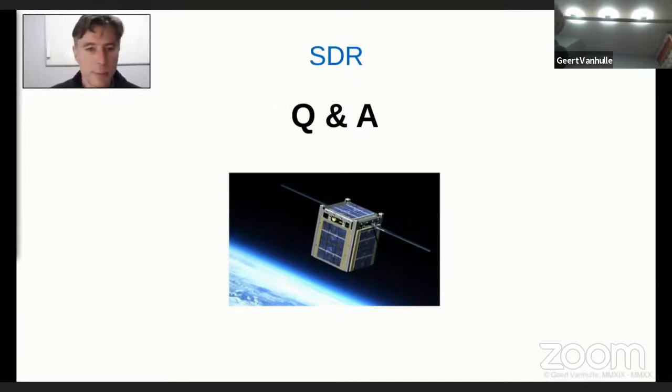The difficulty with analog propagation delays is that they are very nonlinear. So if you have a certain bandwidth, the propagation delay at a certain frequency risks being different at another frequency, which causes a huge set of problems in the analog field. In the digital field, the delay will be higher, but it's linear. So you get rid of a lot of problems on that side.